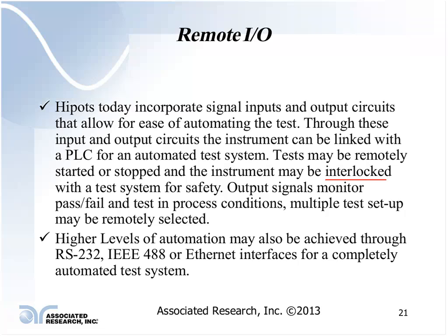They must be visually inspected before each use and electrically tested at least every 6 months, I think, just to make sure that they are in fact safe. So the interlock circuit is an important feature to setting up your product so it is safe, where the operator cannot receive an electrical shock as a result of going through and doing your testing process.